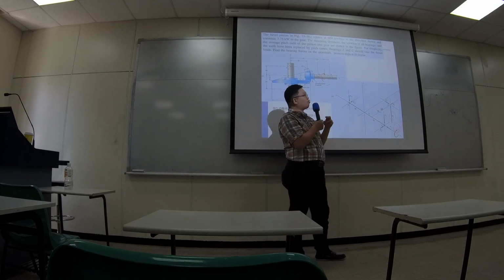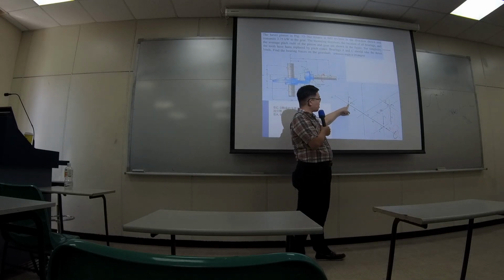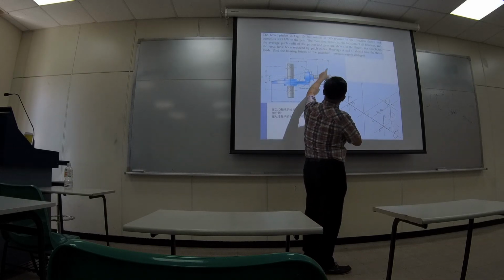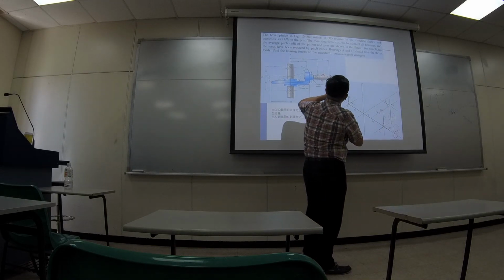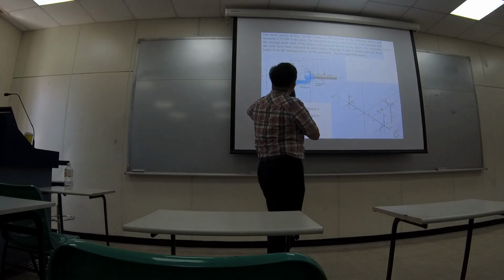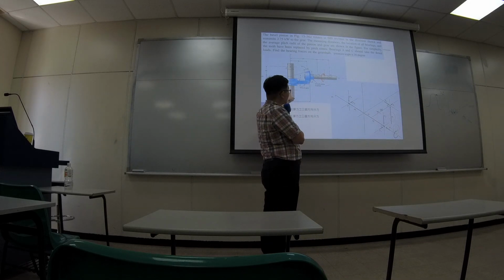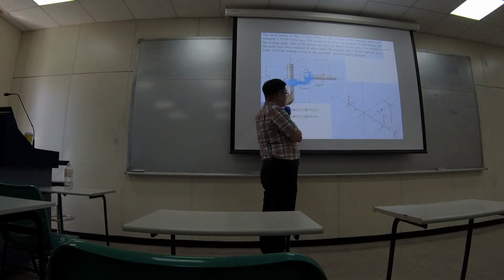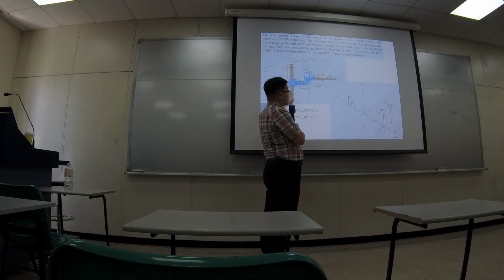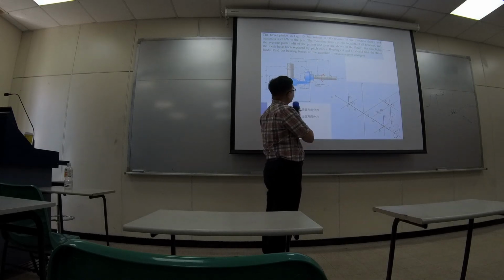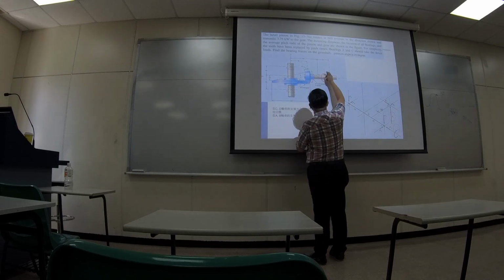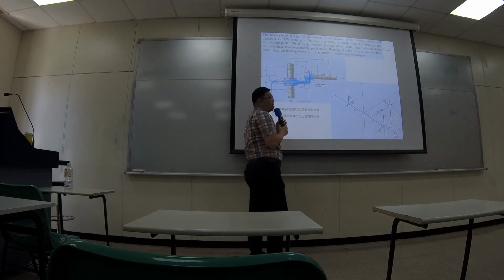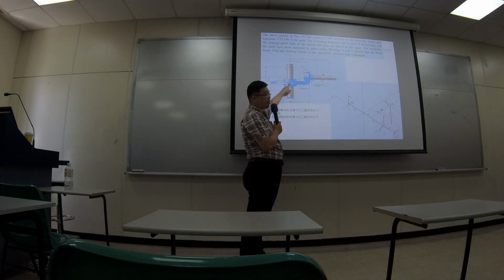So you have reaction forces from the bearings. Actually, in the problem, it tells you there's a thrust force applied to the bearing, but only bearing C is carrying the thrust. What kind of thrust? There's a driving force that is driving the pinion, and there are forces pushing away the bevel gear.